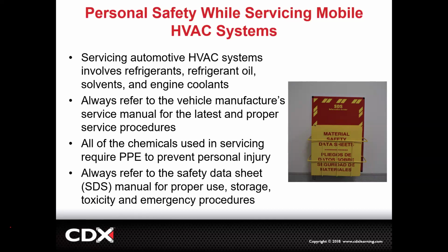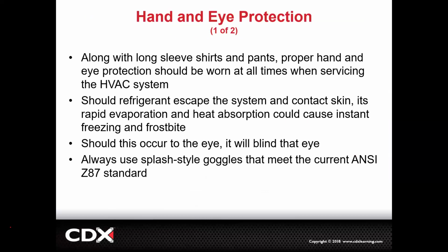But generally, you just don't really want to get it on your skin, mainly because it can cause freezing and literal frostbite, these types of things. It's not the most dangerous thing in the world, okay? But of course, we're going to use PPE, for example. Hand and eye protection, they recommend long sleeve shirts, the correct types of gloves, eye protection. Remember, if the refrigerant escapes the system and contacts the skin, there's such extremely rapid evaporation, it can actually freeze your skin, and it could cause instant frostbite.